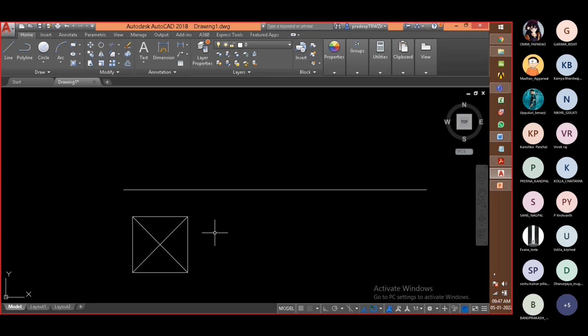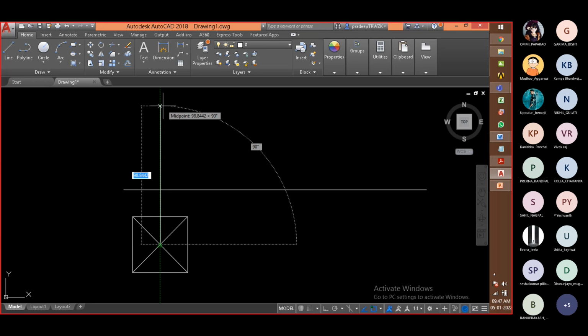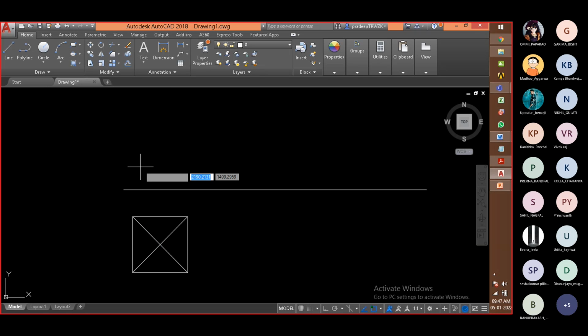Afterwards, I am going to create a line from this point, which may be roughly around 120 millimeter. And if you need to create a correct dimension of 60 millimeter, then you can use the line command. As we have already activated the polar tracking, we can get this intersection over here, then activating my ortho option and 60.